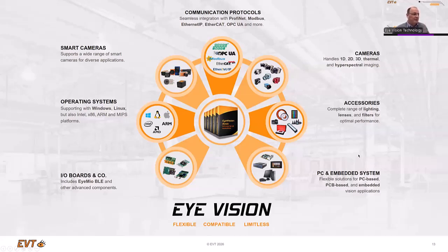The advantages are mostly if you have endless material, or material which is handled on a production belt where you need a very high resolution. In both cases, line scan cameras are the better solution for the application.